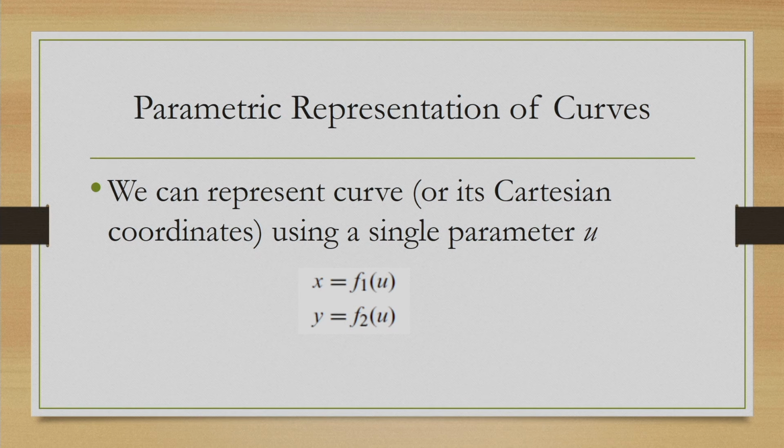How can we represent curves in general using parametric form? We can use a single parameter, which we will denote by u, to represent the curve or its Cartesian coordinates using these equations. This one is for representing the x coordinate, the other one is for representing the y coordinate, where x is a function of u and y is another function of u.